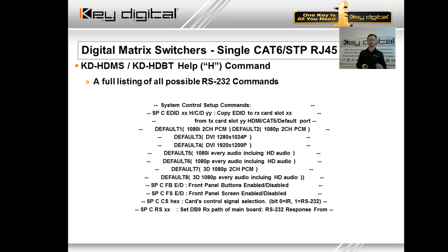This SPC RSXX is the response. Of course, assuming we're in HyperTerminal right now, you issue a command and that response comes from our matrix, right? When you get this help response, for example, or the status response, or even just issuing a switching command and getting that response from our switcher. However, if you have a projector that's connected via RS-232 and you'd like that response to come from there, then we can do that. Not a problem.